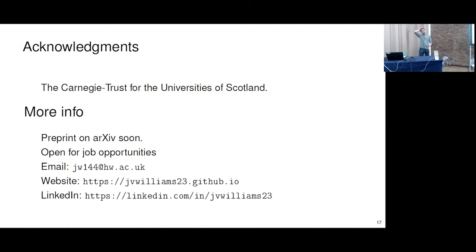Well, first of all, if the particles are colliding, this is 4-way coupling, right? But first of all, there needs to be an adaptation for 2-way coupling. So you need to include the solid volume fraction, for example, maybe relative distance between particles. There are some physics-based models for 4-way coupled dispersion in RANS.